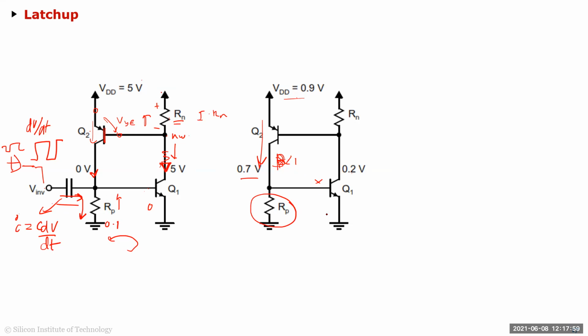Because if you change the doping concentration, your VT will change or your mobility will change, and you don't want that to happen, because you don't want to degrade your devices as well. I mean, it's always a balancing game. So you drive that to the maximum you can, and even after that, you'll still be left with certain betas which are greater than 1.